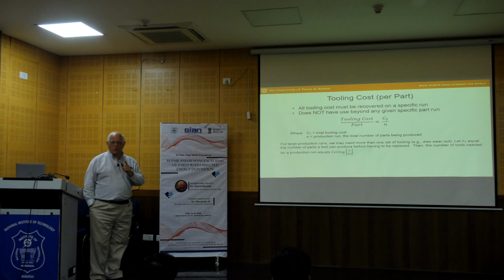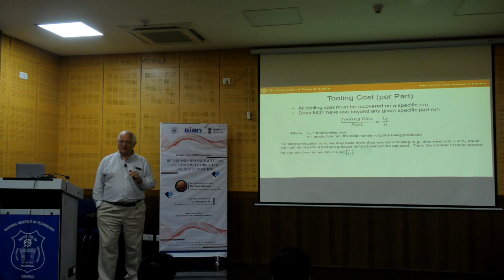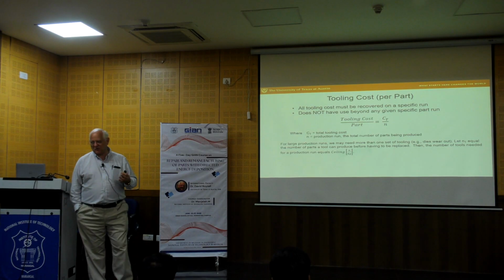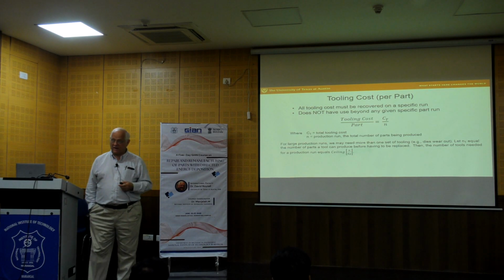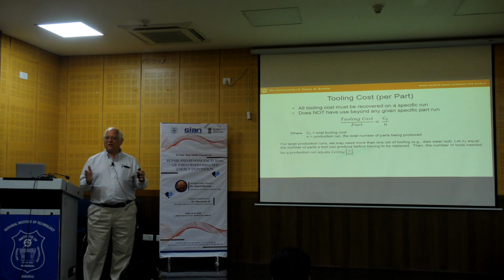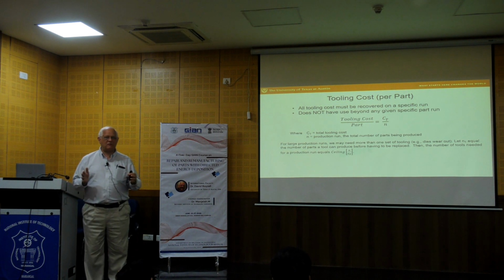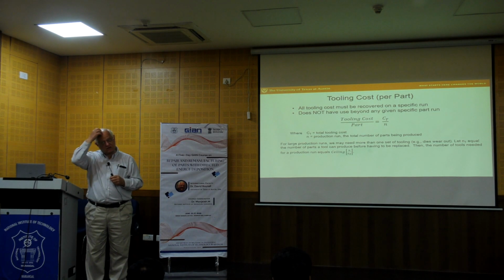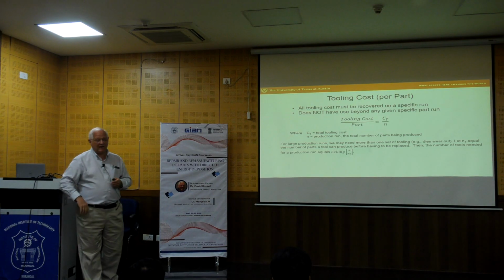But there's one sort of glitch in this, and that is if we have a large production run, which typically is not the case for additive, it turns out I may wear out the tool, right? The tool may only be good for 500,000 parts, and then I have to replace the tool. And I'll have to do that if my production run is large, like 5 million parts I want to make. I may need 10 tool sets to complete that process.